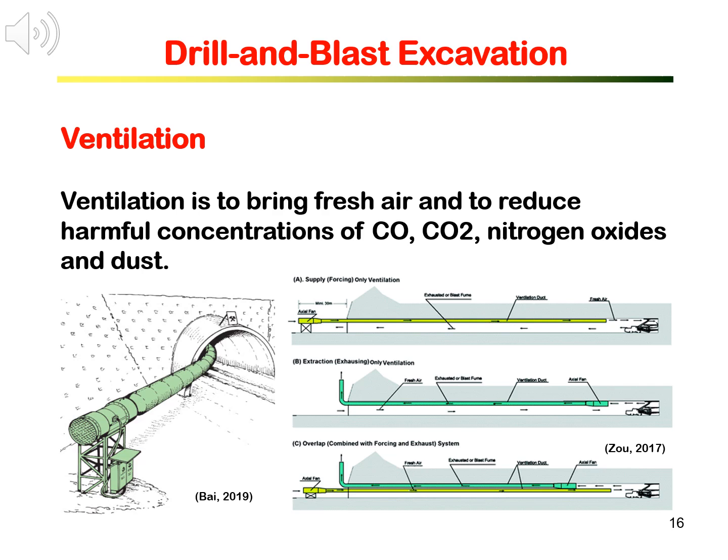It can be done by pumping the fresh air into the excavation area and pushing the harmful air out, or by sucking the harmful air out, or a combination of both. This is illustrated by the figures below.